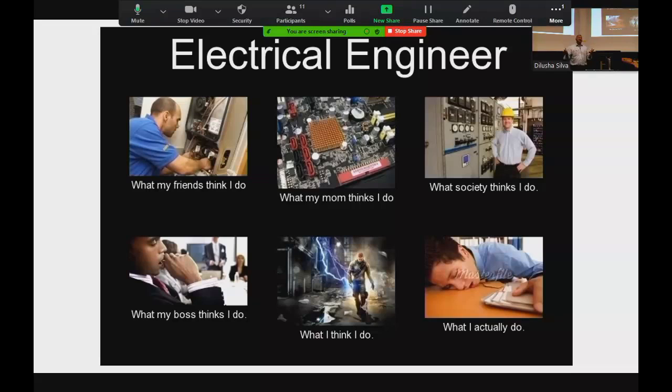Because fundamentally fuses, unfortunately nowadays, within a normal electrical network, don't exist anymore. Right? They're very old. But fundamentally, you should be looking at the load and the characteristics. In high voltage installations, so 6 kV and above, main distributed networks, we still use fuses. All right? But fundamentally, you should be looking at the characteristics of what you're to supply.